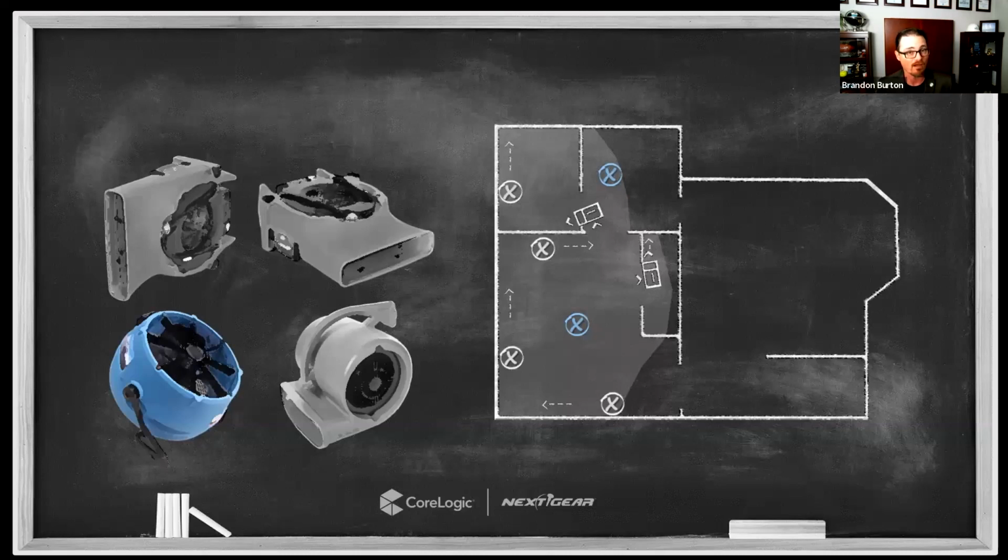So take a couple of hygrometer readings to validate that, but you can also use your hand, believe it or not. What you're looking for is sensible airflow at the wet surface, sensible airflow. And sensible airflow means that your hand is going to feel the effect of airflow because of the byproduct of evaporative cooling, which is exactly what you're trying to do to the wet surface. If there's enough airflow to make your hand feel cool because the moisture is leaving your hand as air moves across it, then you have the effect of evaporative cooling. There is enough airflow to remove the sweat, the evaporating moisture from your hand, and create that sensible cooling as that moisture and energy leave.